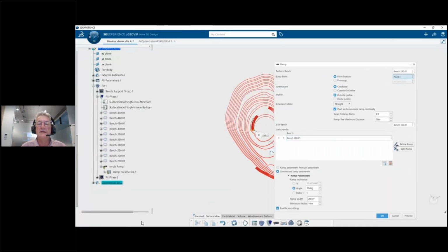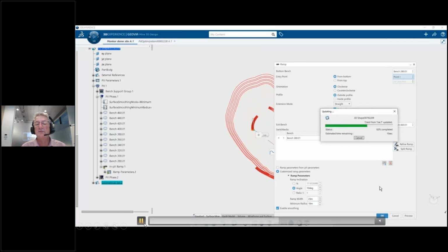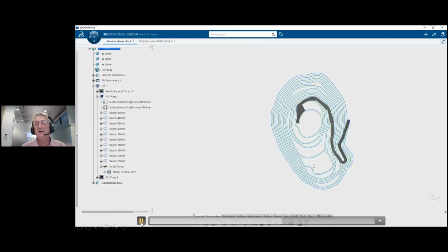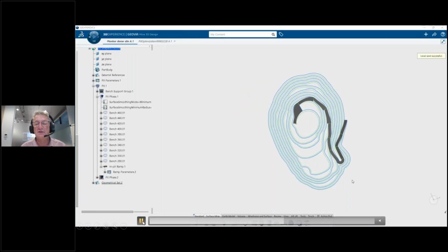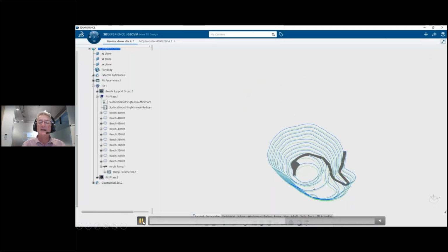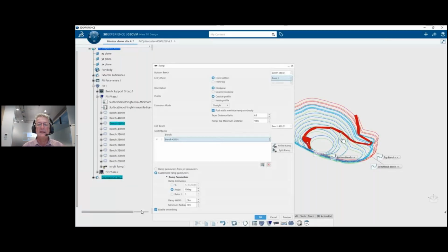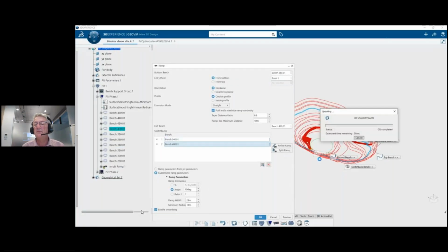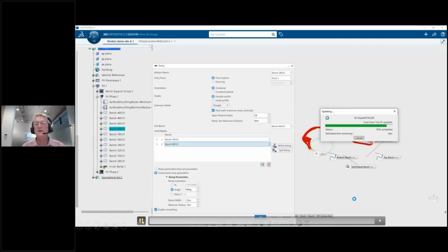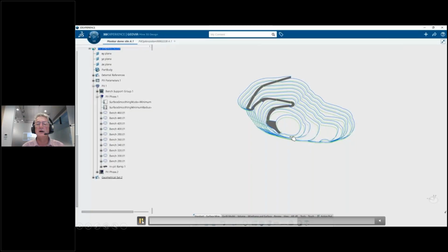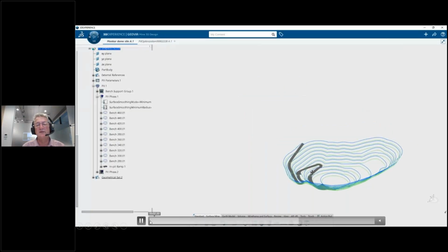There is an automatic switchback definition, which allows us to change the direction of the haul road at a particular elevation without having to edit the design by hand. So that is linking the crests and berms to the position of the haul road. We update the position of the haul road, the design updates itself.